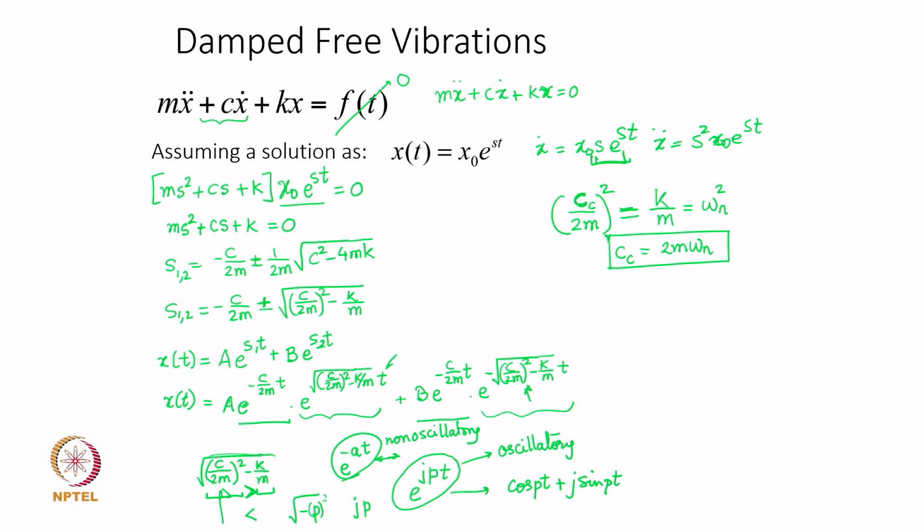So, it makes more sense to introduce a term called the damping ratio, mostly denoted by zeta, as C over Cc. So, it is basically a normalized damping of the system. Normalized why? Normalized with respect to Cc. You may notice that for a given system, this critical damping coefficient is a function of the system parameters like m, k.